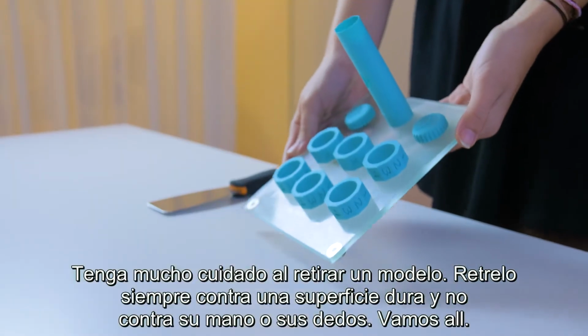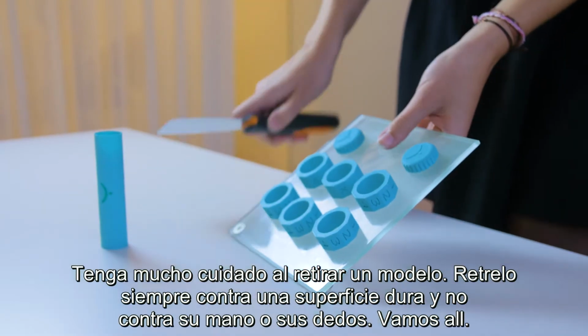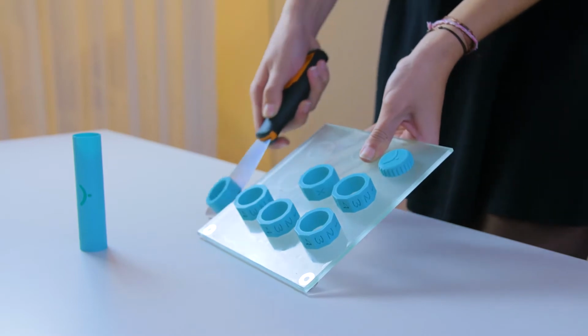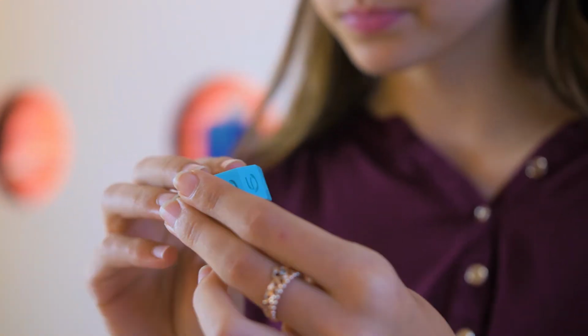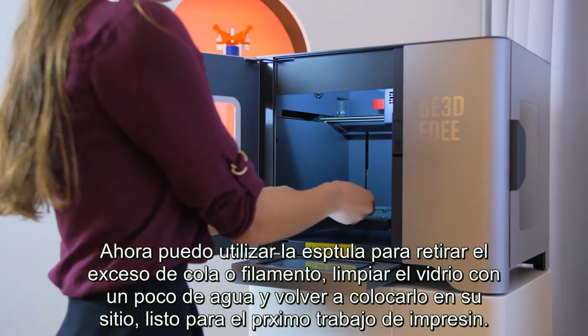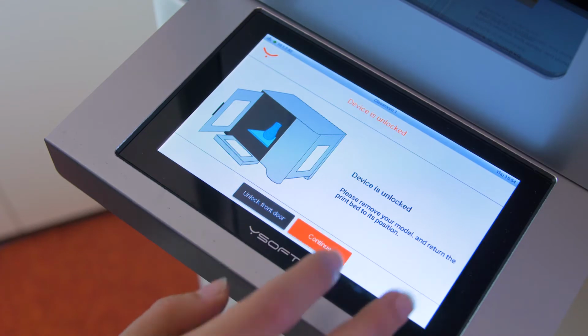Be very careful when removing a model. Always remove it against a hard surface and not against your hand or fingers. There we go. Now I can use a spatula to remove any excessive glue or filament. Clean the glass with some water and place it back ready for the next print job.